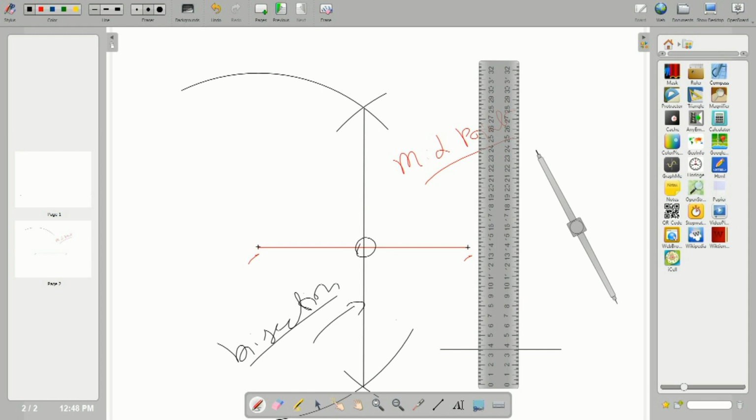So, what about an arc? In a similar fashion, if you consider any part of a circle, I just erased this arc. What about the center point for this arc? How to find the center point, how to bisect this? In the same fashion, you take one endpoint and draw an arc from that endpoint. Okay, the needle point is here.